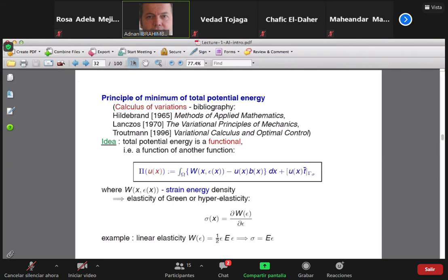So now the goal of this calculus of variation is what? You have a so-called functional. This is not the same thing as a function. U of x is a function. In other words, for every value of x, from 0 to L, you have a displacement field, which is a function of x, and you give a particular value to this function. Now, P is a scalar value. It's the total potential energy of this bar. And it is computed in terms of the argument, which is the whole function u of x. So if you think of that, functional P of u of x is a function of a function. So u of x is a function, and P is a function of this function of x.